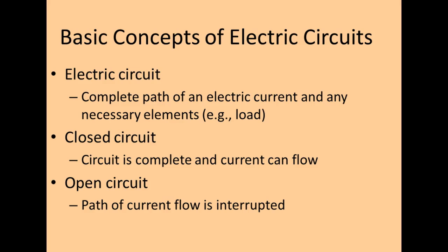And 500 watts. These things are using different watts, so they're obviously going to have different resistance. But the amperage in a series has got to be the same. Okay? And so we'll come back to that. But that's very important. The amperage at 1 has to be the same as amperage at 2, has to be the same as amperage at 3, and so on and so on.